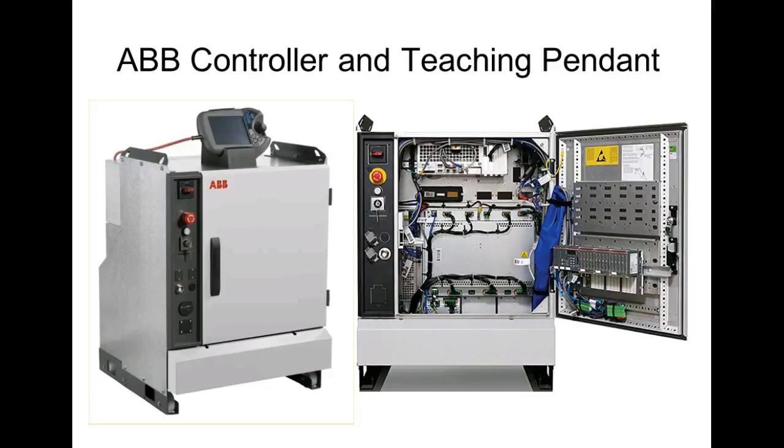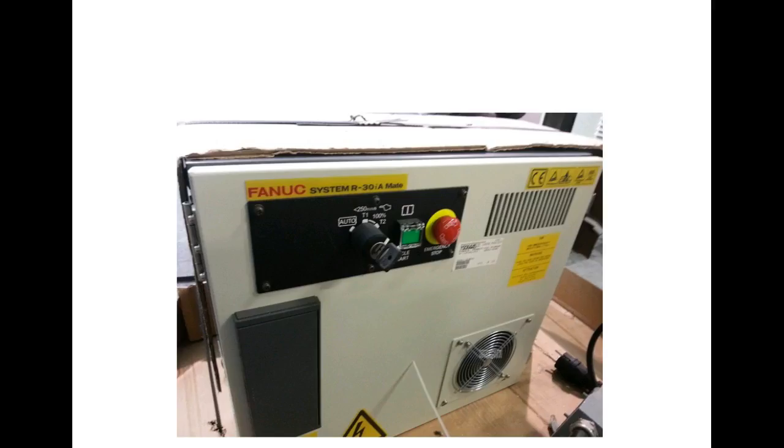We don't have that on our robot, but this one can communicate. This would add all types of inputs and outputs to the robot. We'll show y'all this on the big FANUC. They have a big DeviceNet card up there that allows us to connect a ton of stuff to the robot controller without using up the ports on the robot itself.